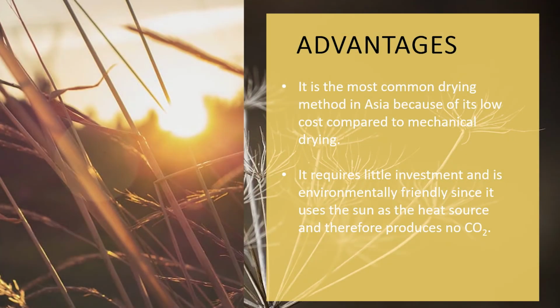The advantages of open sun drying are that it is the most common drying method in Asia because of its low cost compared to mechanical drying. It requires little investment and is environmentally friendly, since it uses the sun as the heat source and therefore does not produce carbon dioxide. Unlike electrical drying, where coal is burned, and because of the burning of the coal, some carbon dioxide goes to the environment and it is not environmentally friendly.